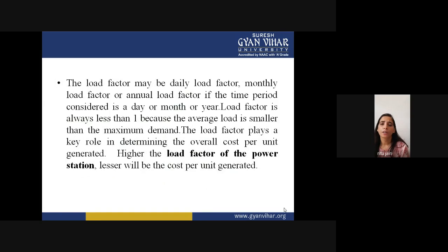So the load factor plays a key role in determining the overall cost per unit generated. Higher the load factor of the power station, lesser will be the cost per unit generated. If your average load is always minimum, then the load factor will always be less than 1.